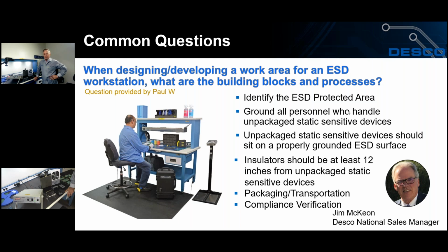Greg, can you demonstrate how packaging, ESD shielding packaging works? Yes. So here I have a static shielding bag. Now, that's something important to understand. Here I basically have a low charging, or a lot of people might call it an anti-static bag. And the main difference between the two is this won't generate a charge, but it will also allow a charge to go through it.